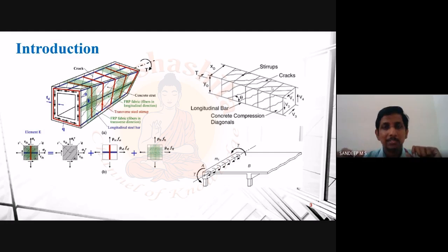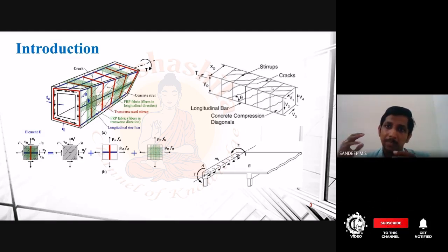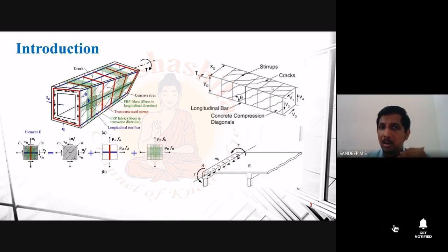When a beam is failing in torsion, you will observe cracks approximately inclined at 45 degrees on all the sides of your beam. This torsion is completely twisting the section, so you will observe these types of cracks all around the section. Suppose you go to a field and see that one beam has failed and cracked, and you observe 45-degree cracks on all sides of the beam. You can conclude that there is an effect of torsion. That might be a combined effect of shear, torsion, and other things, but there is an effect of torsion because you are observing cracks on all sides of your beam.